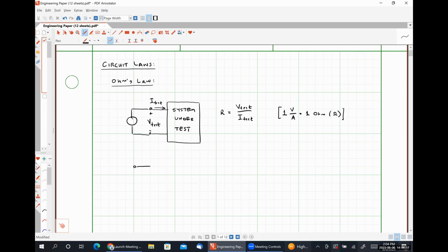and this is the schematic symbol for a resistor, which you're likely familiar with. So if we have some resistance R, and let's say that the voltage drop across our resistor has this particular polarity, and the current flowing through our resistor is in this particular direction, so that the current is flowing into the positive polarity terminal, then we will express Ohm's law as the voltage drop across the resistor is the current flowing through the resistor times the resistor value.